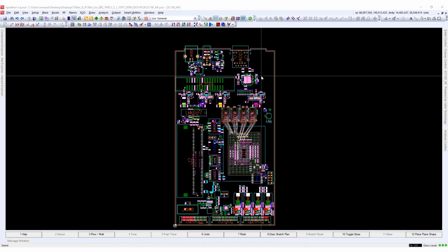Zach finished the fan-out and breakout of all DDR4 DQ signals coming from the memory chips to the FPGA, and our SI-PI expert Rory verified the power integrity of the P1V2 power net of the DDR4 circuit. Based on this, I want to do the second FPGA pin optimization step to reduce the last netline crossings and to pave the way for sketch routing, which is done by Zach later.